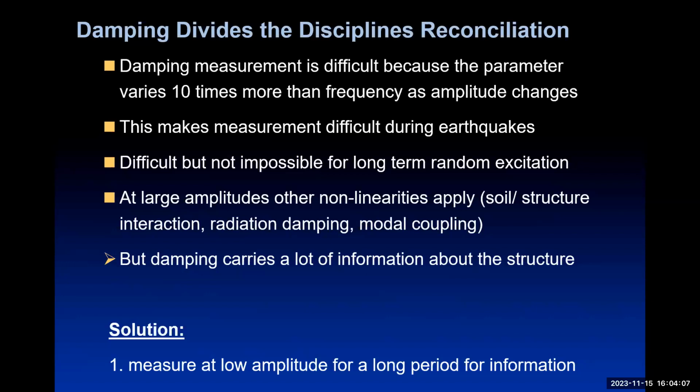Because wind engineers have been used to measuring the response of structures over long periods and say, yes, we can identify what damping is. Earthquake engineers say, we don't have enough data. We only have a few minutes at the maximum when an earthquake is going through. So what we do is say, yeah, okay, we'll take an average value.